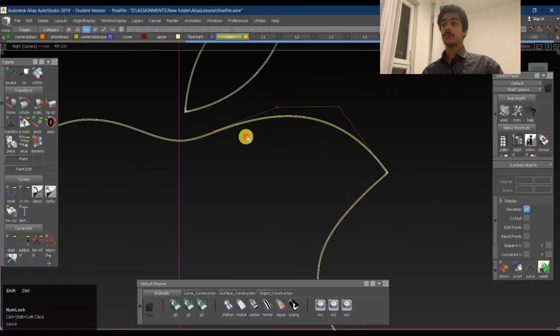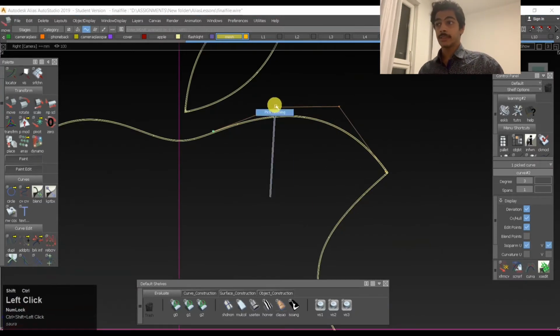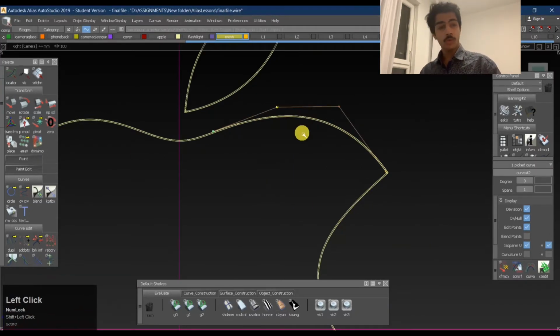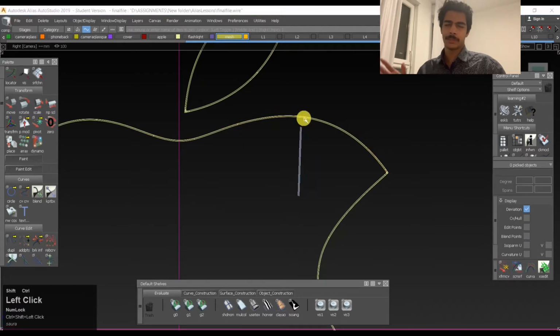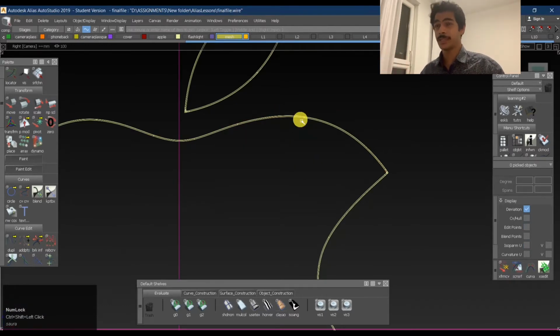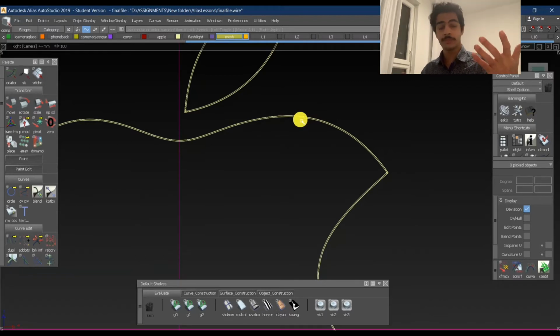The major thing with cutouts like the logos and stuff is that they're bound to have spans, right? It's going to have spans because anyways we won't be creating very rigid surfaces out of it. It's just going to be planes and stuff. So we don't care about the spans a lot because, as I told you in the previous one, once you project a curve on a surface, it's going to have spans anyways. So you just create a very free form kind of a feel with it.